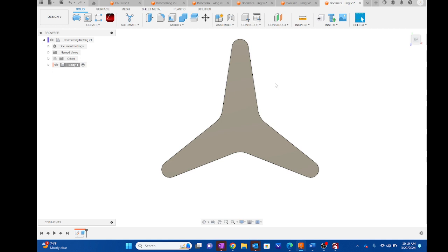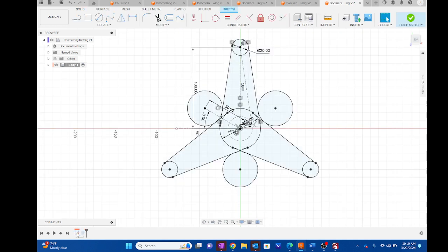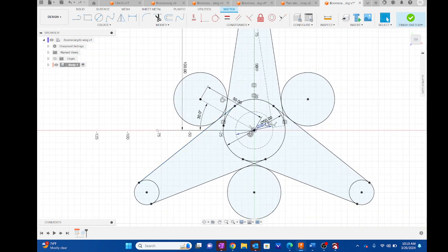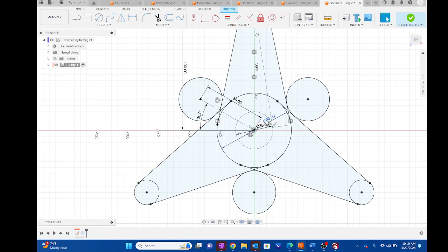Now, let's say, for example, you're not really loving that design, so you want to get in there and make some alterations. Same thing again. Come down here to the parametric timeline. Remember, this is like your history timeline. Okay, double click on your sketch, and then you can go, well, maybe we can make this center diameter a little wider. We'll go 60. See what that does.